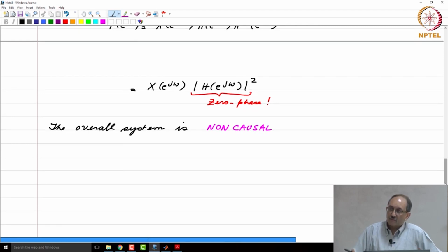And phase response being nonlinear gives rise to this group delay, and the other important point is that even though the magnitude response may be constant, if the phase response is nonlinear, it can cause wave shape distortion, right.